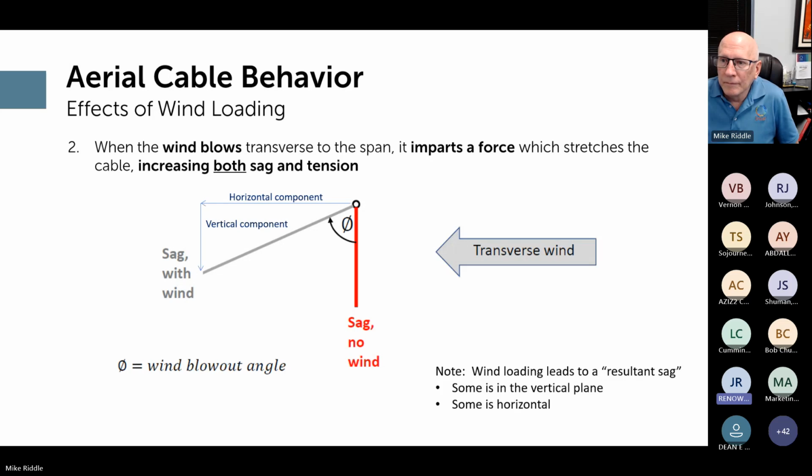Is it in series with a come-along that's pulling the conductor up to final tension, or is it down on the puller itself, which is reading the tension going up to the first set of blocks instead of the horizontal tension on the span?